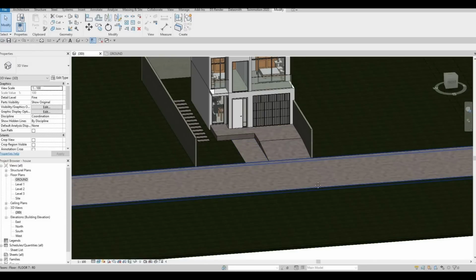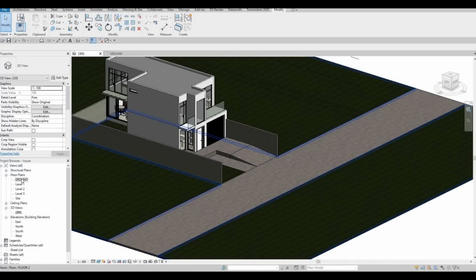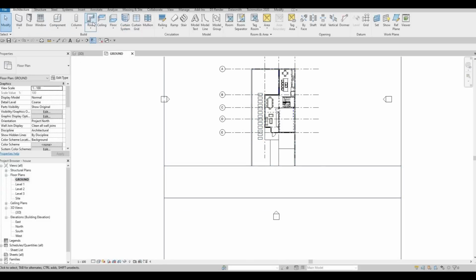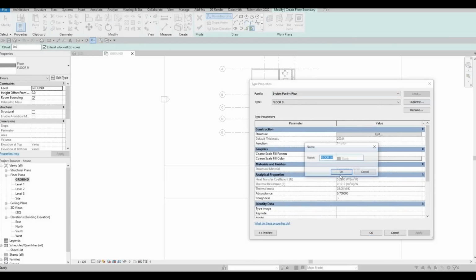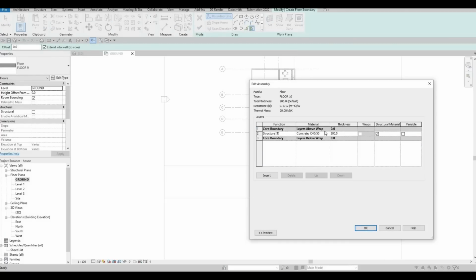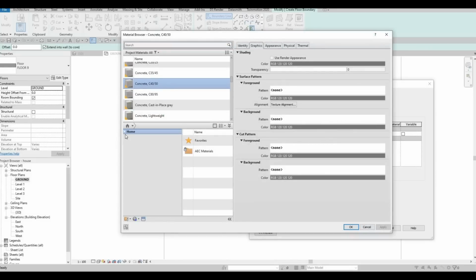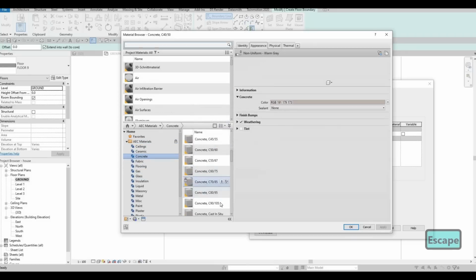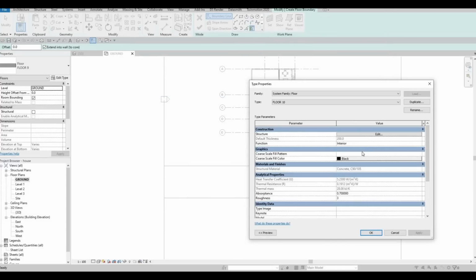And then we're going to add in the side street or the sidewalk. What I'm gonna do is add in another floor: edit, duplicate, floor number 10, and then this will be another concrete material. Pull it up, click apply, OK, and then OK.